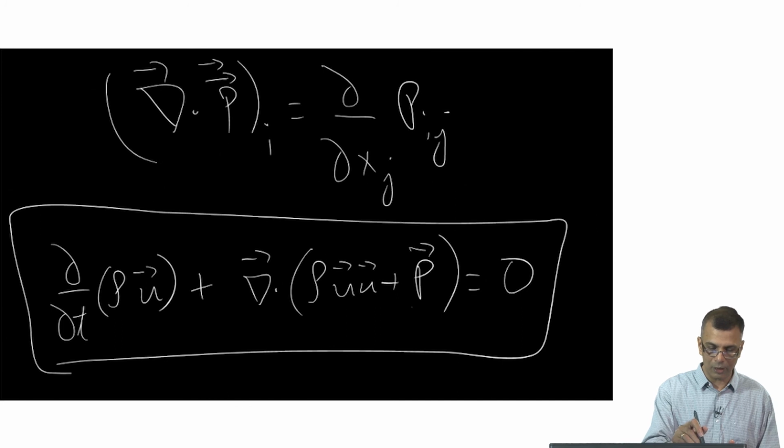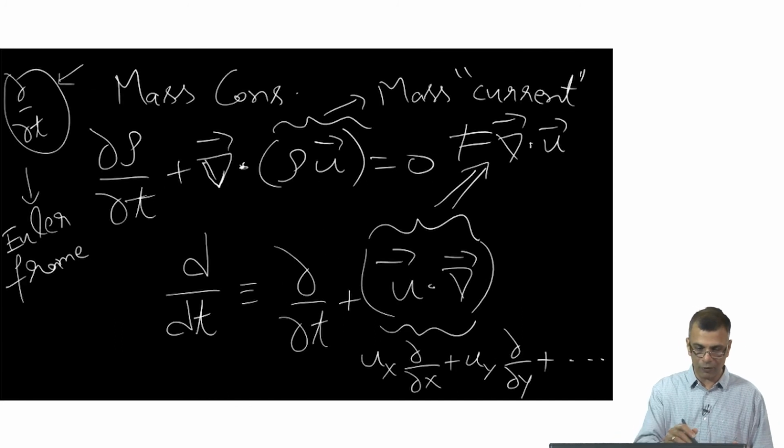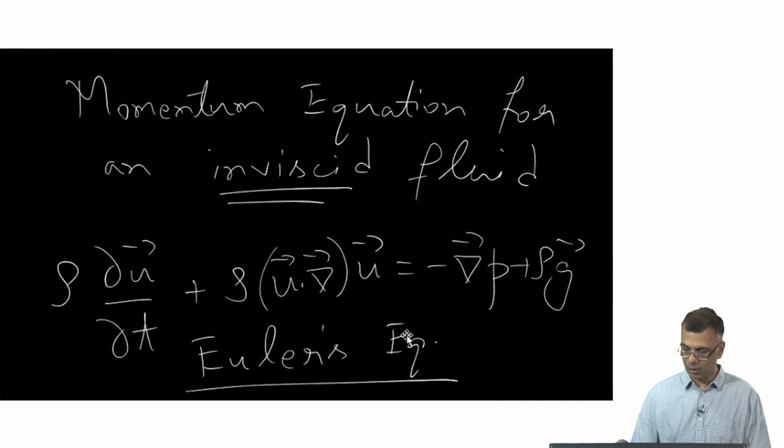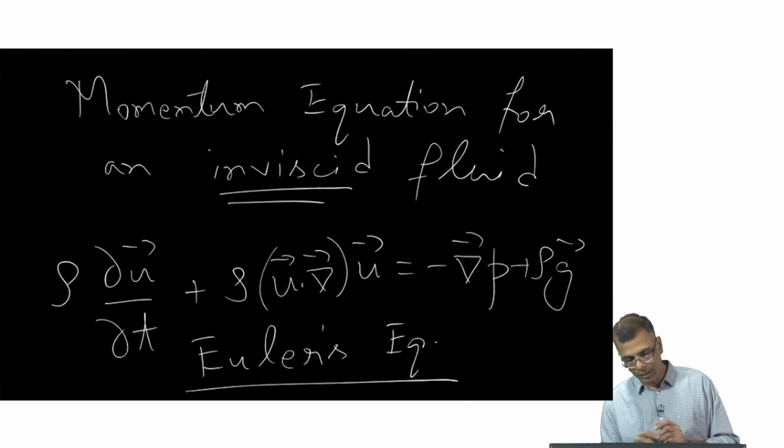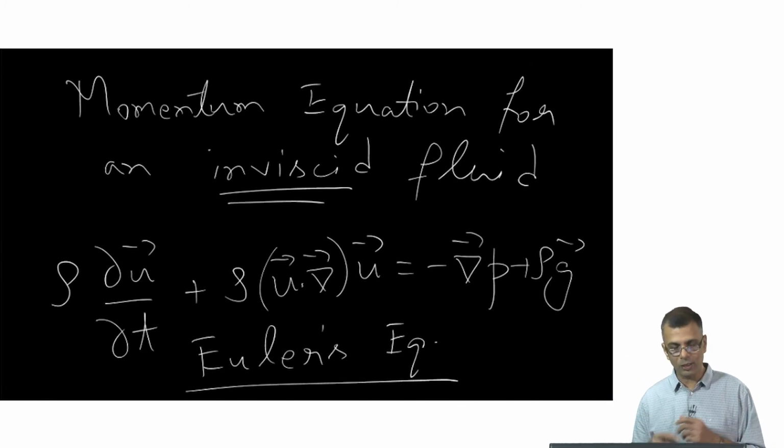Now, if you recall the difference between the Eulerian derivative and the Lagrangian one, and you look at this definition, you can quickly see that it's possible to write down this equation in Lagrangian form also. You saw the advantage of writing down the momentum equation in the conservative form in an Eulerian frame, in other words from the perspective of a lab observer.